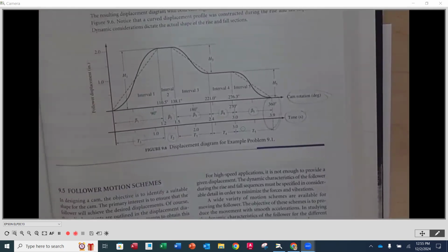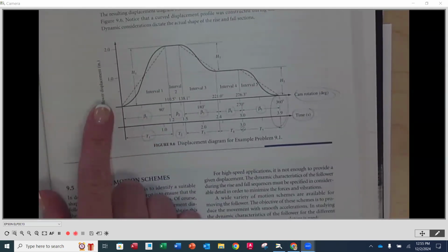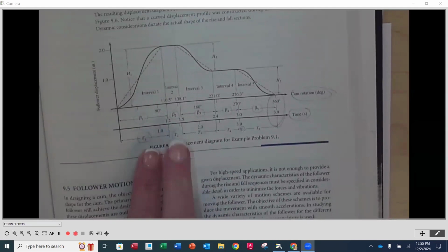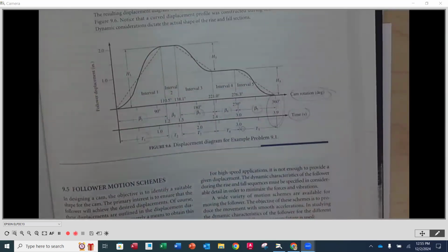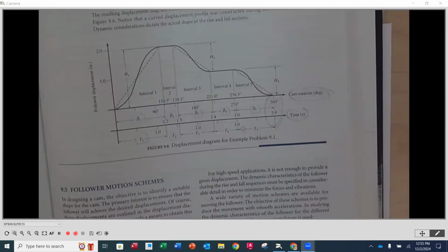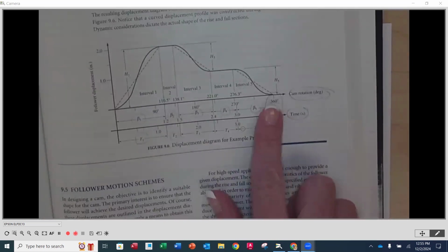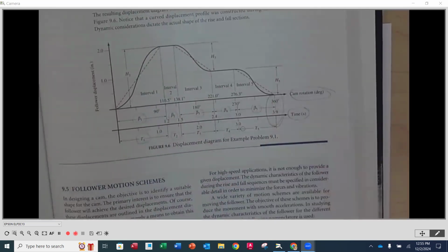What you want to do is make your axis about 3 times whatever that height is. So in this case, if it's 2 inches, you want to make your x-axis 6 inches long. And then just divide that by 360 to know how much of that 6 inches is going to be a single degree. Does that make sense to everybody? And then you mark off however many degrees. So then you would take whatever it is per degree, however many inches that is, and you would multiply by each one of your betas to get each one of those lengths. Okay.